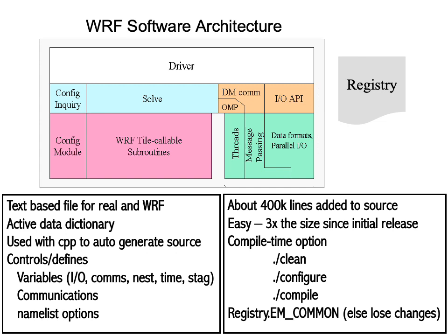This may sound daunting, but it's actually apparently very easy. The registry itself is 3 times the size that it was from its initial release. So a number of developers have been able to put a large number of fields inside of the registry. Anytime the registry file is changed, that means there has been an attempt to modify the source code in the WRF model. Any change to the registry means that a user is required to go back, completely clean the source code, and run configure and compile again.